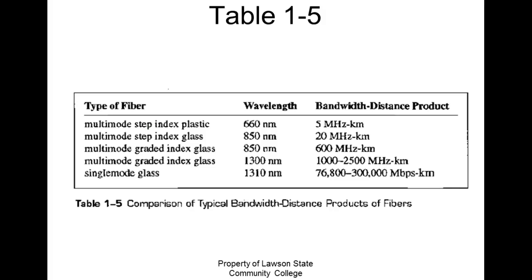Now, single mode glass, which we have some over there, I need to go over and get it, 1310. Of course, you can't tell the difference between single mode and multi-mode, because what they do is all these right here run a 125 micron cladding.